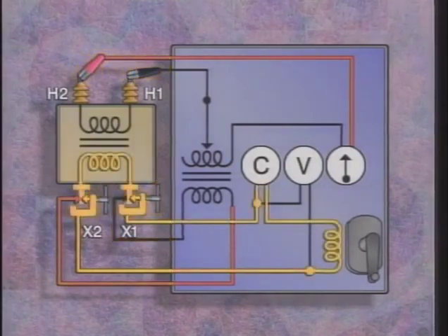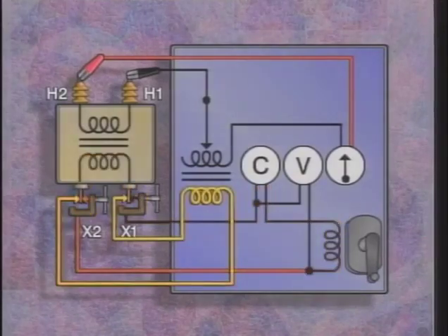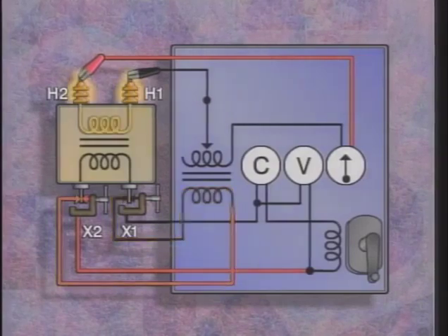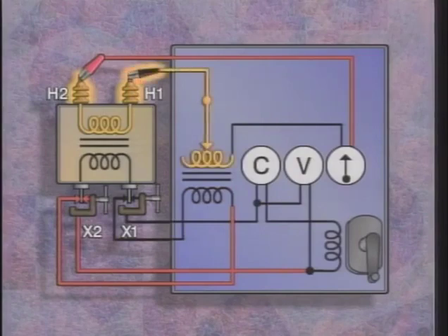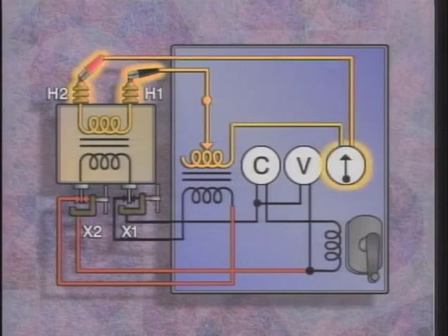Also included in this illustration are test leads. One pair of the test leads, called the exciting leads, contains 2 conductors that are used to apply voltage from the generator across the low voltage winding of the power transformer. These same test leads contain another 2 conductors that are used to apply the generated voltage across the low voltage winding of the reference transformer. A second pair of test leads, called the high voltage leads, connect the high voltage winding of the power transformer with the high voltage winding of the reference transformer and with the null detector.